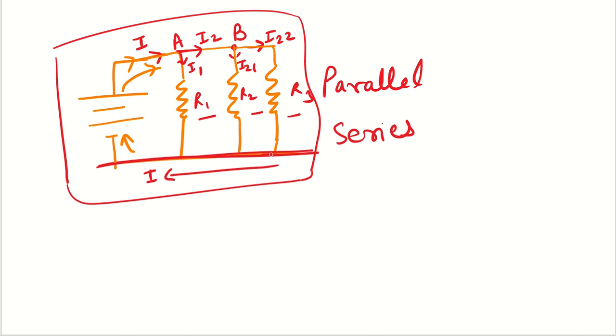Since this conducting metal sheet, or the chassis ground, we have connected this to ground, so we call it chassis ground, right? We have connected this part to the chassis ground, or to the chassis. Therefore the potential on this side we will consider as 0 volt, right?